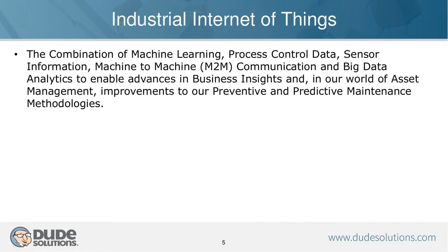Probably the simplest example, and I've been in the industry for 20 years, I remember in my first year going out and actually doing a little bit of the industrial Internet of Things. I was integrating a work order management system with Wonderware, and taking the operational parameters that Wonderware was tracking and then generating work orders if those parameters got out of set points or had a failure or error code, to create work orders automatically.